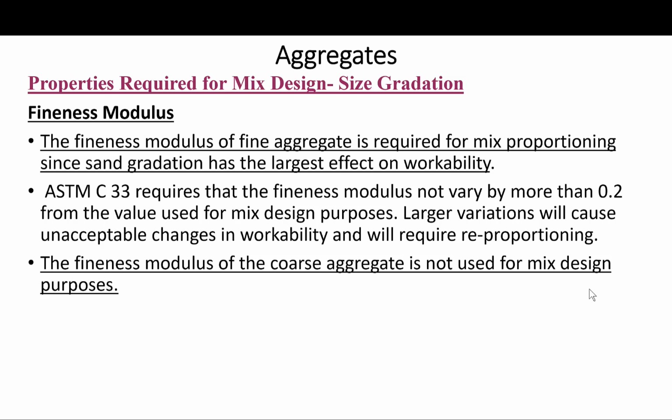The ASTM C33 requires that the fineness modulus does not vary by more than 0.2 from the value used for mix design purposes. So larger variations will cause unacceptable changes in workability and will require reproportioning.